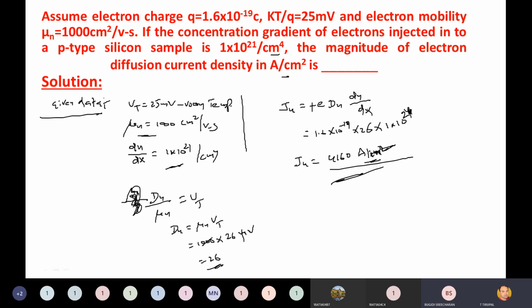Don't cancel out like that. You just simply write what are the final units of this, isn't it? So finally what do you need to find? Current density. Whatever you substitute, you get it cancelled, ultimately the final units are amperes per centimeter square if it is given in centimeters, or if it is given in meters, then you will get amperes per meter square.